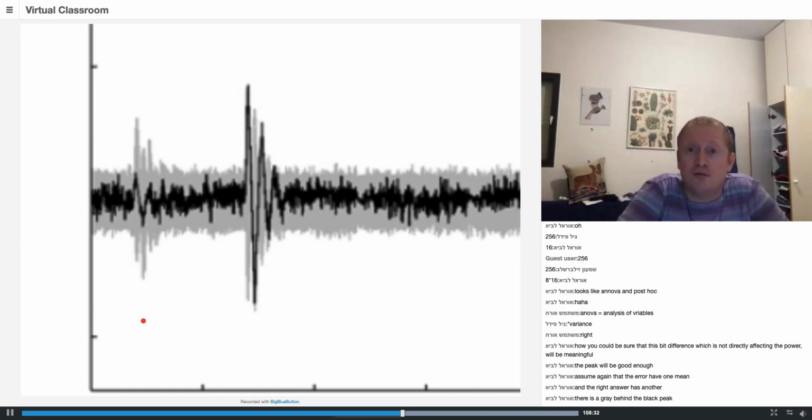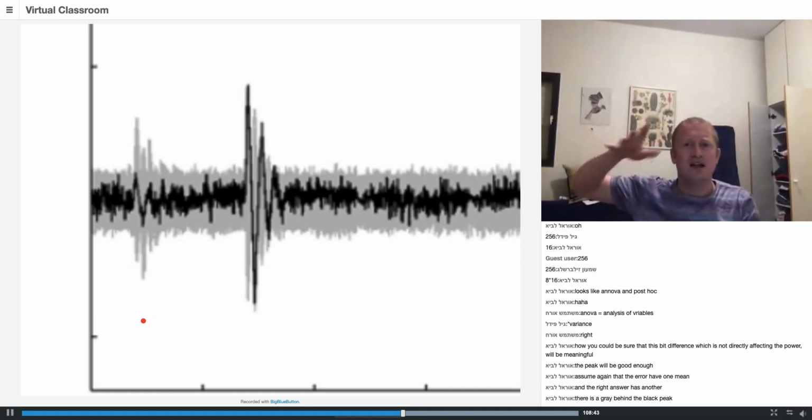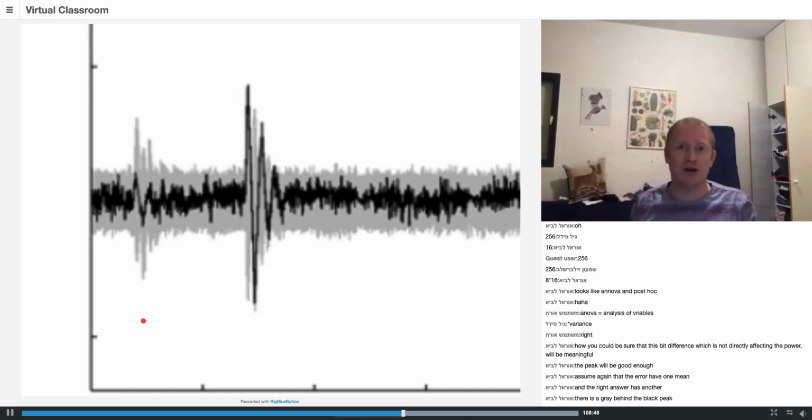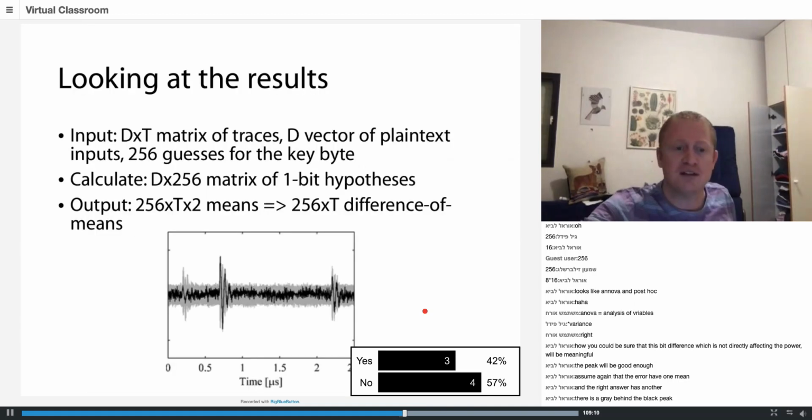And it could be that you're not very good at rejecting traces. So if you recall, one of Stefan's graphs from last week had the x-axis as the number of traces, and the y-axis as how good the correct key was in comparison to the incorrect key. So when you're adding more and more traces, hopefully you're going to be able to reject the incorrect key well. But indeed, this is a problem. You have ghost peaks, and you have incorrect key guesses getting through. So you might need to do some post-processing, even though you used a statistical method, you might have several key candidates. You might need to reject